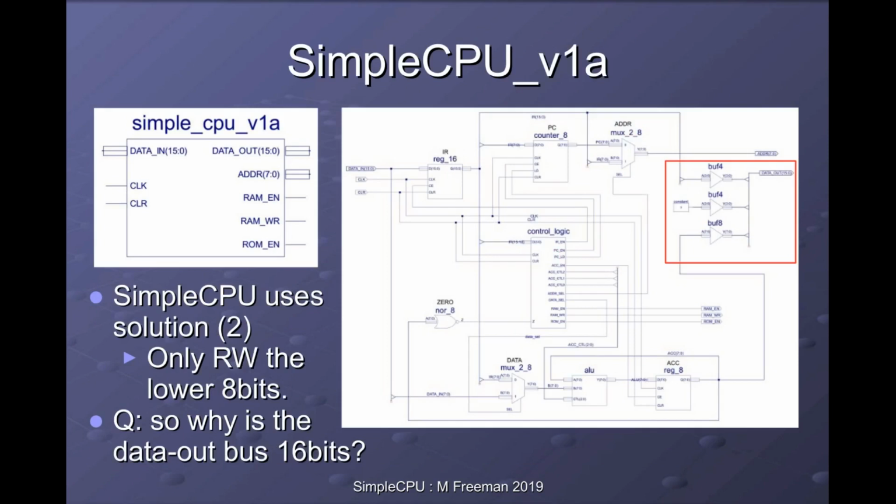You could argue, why have I got a 16-bit data bus then? Because instructions are only 12 bits, as instructions don't actually use the low nibble of the high byte. And the reason for that one is we do use those extra bit fields in later processors, so that's why I went for a 16-bit address bus.